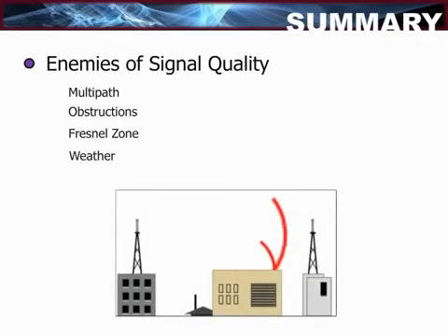Multipath is essentially an echo of an RF signal. Multipath situations can become extremely complicated and impossible to predict. The first step in combating multipath is to simply move either RF device involved in the link, even if it is just a few feet. Changing channels can also affect multipath situations.